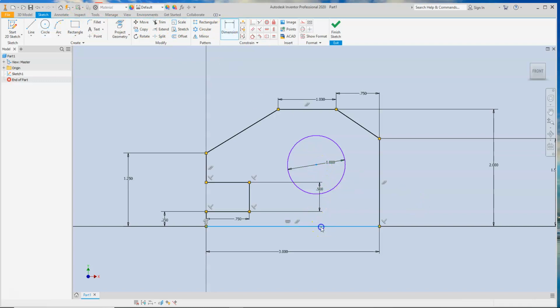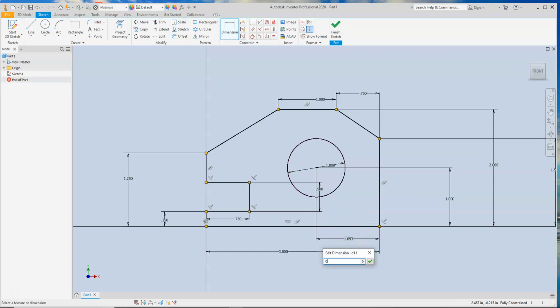And even if it's something where you're given a radius, Inventor is going to reference a circle or an arc as the diameter. So here I'm just pointing to the center of the circle and the vertical edge, and I'm laying out the dimensions that were given. Oops. So I get this all here. So I've laid out the basic geometry here. I'm going to finish the sketch.